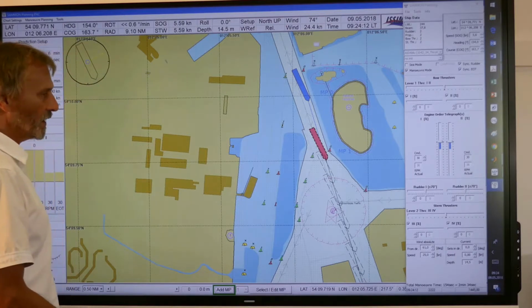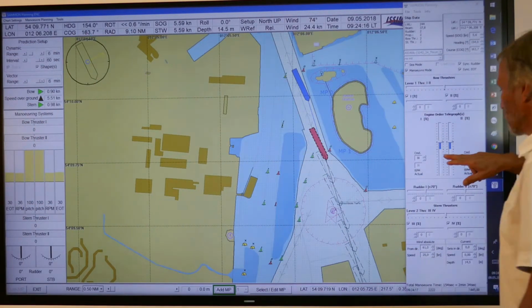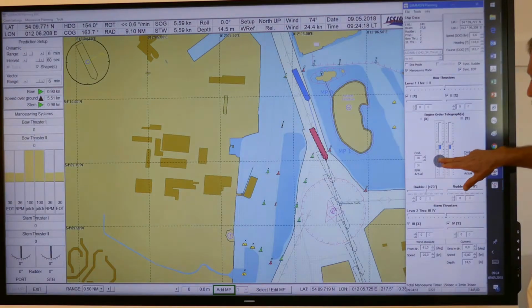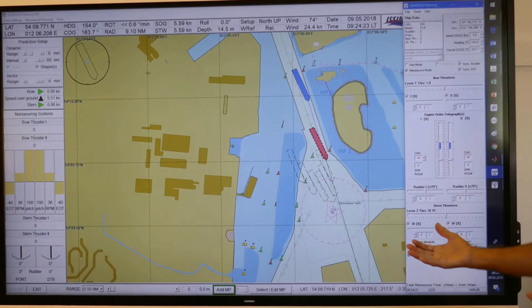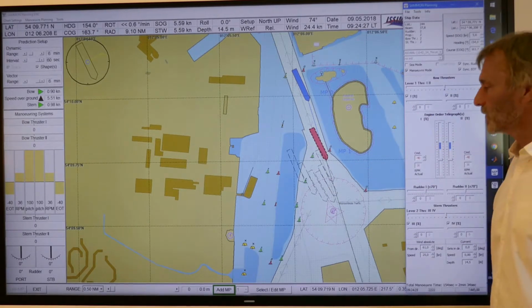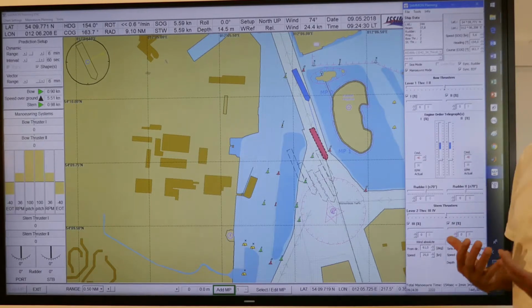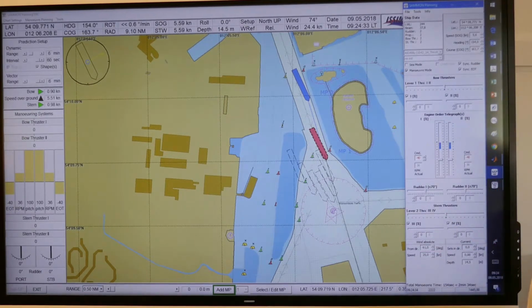If we stop the engine, then what would happen? In the previous maneuver it worked. So we went to minus 30, but here you see immediately this won't work, because due to the tough wind, the ship is drifting in this direction. So we need some counteraction. The first idea would be, okay, let's only use the rudder. This won't help. So no chance to help with the rudder.